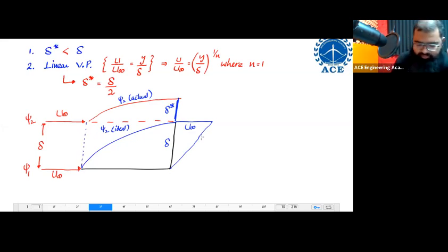Please understand this: mass flux m dot 1 corresponds to this particular rectangle. Is it not? Mass flux means what? Density, let us say it is constant, into area. Area over here is equal to this height multiplied by the width perpendicular to your screen multiplied by velocity. Velocity is u infinity throughout.